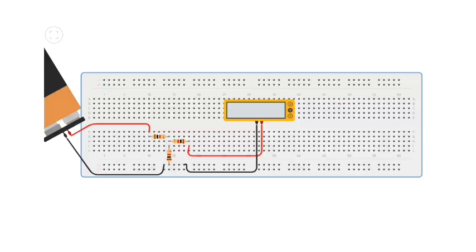So this is how your circuit for calculation of Thevenin's voltage would look like. Fine. This is your voltmeter. The source is connected to resistance R1 and another terminal is going here. We have simply removed resistance RL and put a voltmeter across those two terminals, and whatever reading this voltmeter gives, that will be our Thevenin's voltage. We are going to write it down and proceed to the next step.